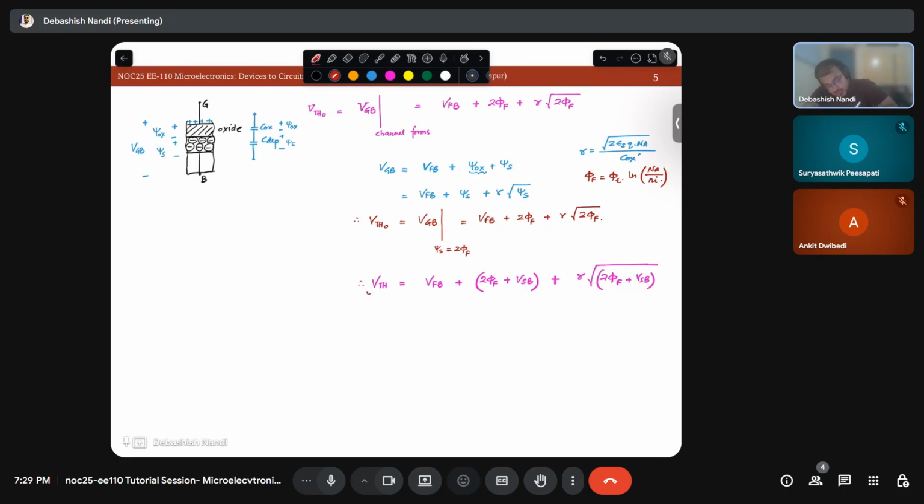So this is basically your VGB, right? At some VGB, let's say. Now if I want to calculate VGS, what is VGS? VG minus VS, right? So can I write VGS is equal to VGB minus VSB?